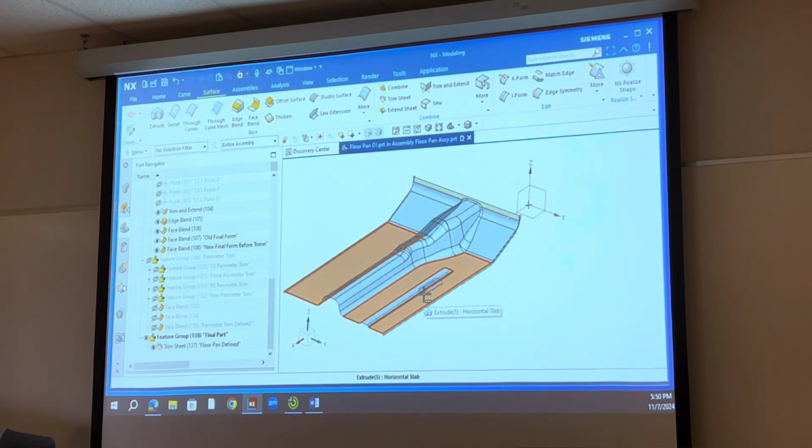And again, just in case anybody here is also in CATIA classes, in CATIA, if you're going to do something after the fact like that, you have to tell it with a separate setting, a separate switch, that you want to insert this in the middle of the history. If you don't tell it that, it's not going to insert it between things, it's going to add it to the history.